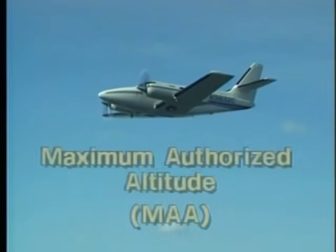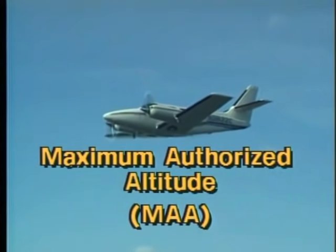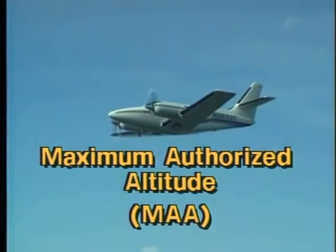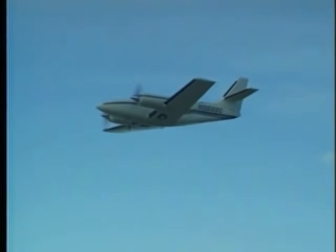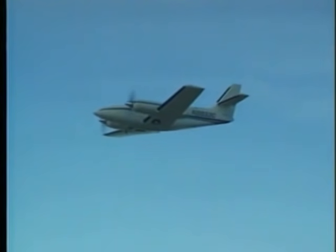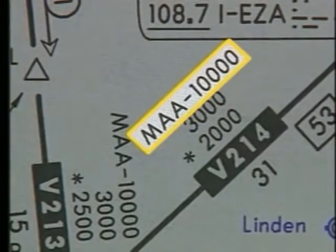In a few cases, maximum authorized altitudes, MAAs, are specified. These normally occur below special use airspace or because two VORs transmitting on the same frequency cause signal interference. They are indicated by the letters MAA, followed by the applicable altitude.